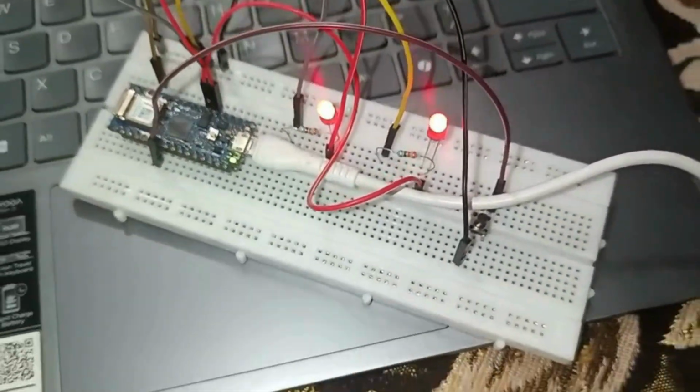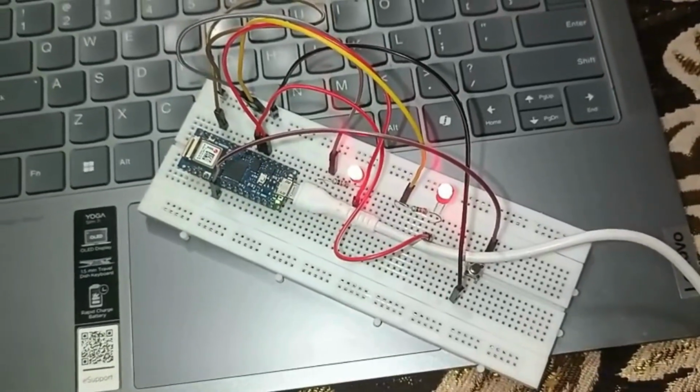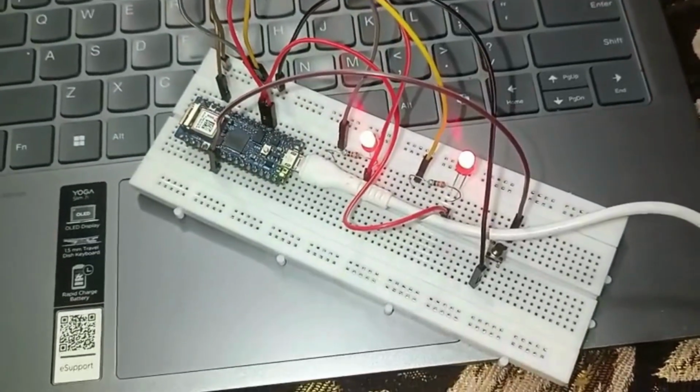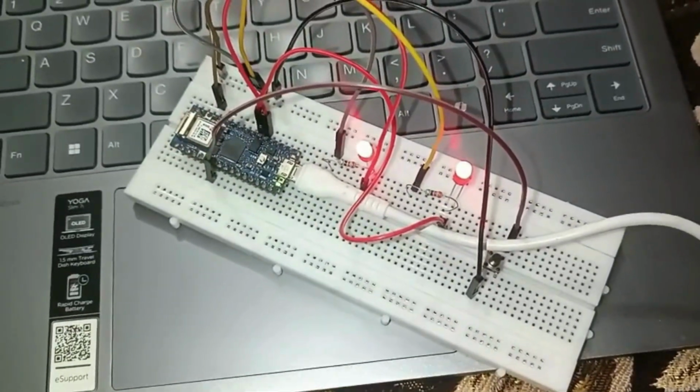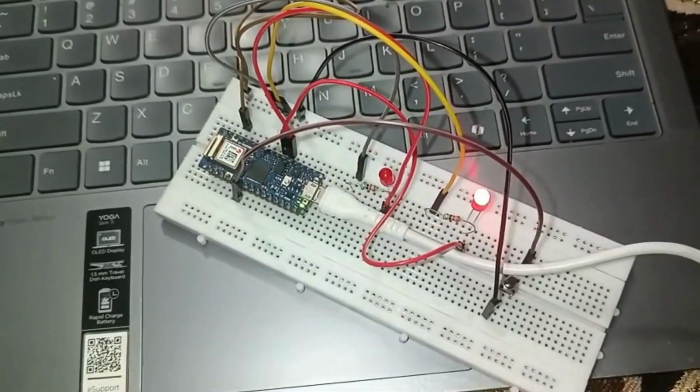Here is my circuit for the smart lighting system. The push button is connected to D3, the porch light is connected to D16, and the hallway LED to D17. With the resistors, which are used to limit the LED current, all the components share a common ground. When the button is pressed, both the lights are activated.